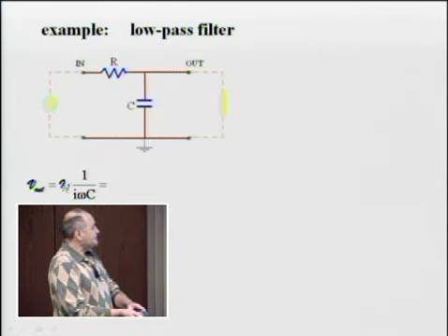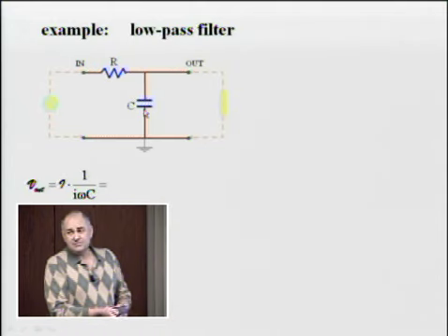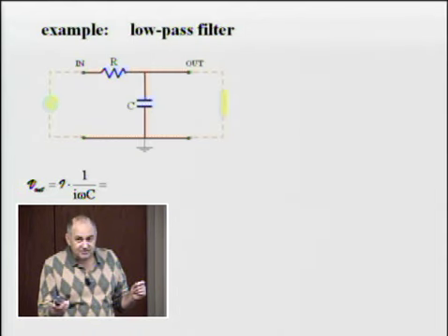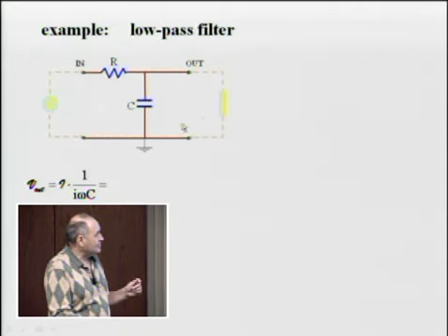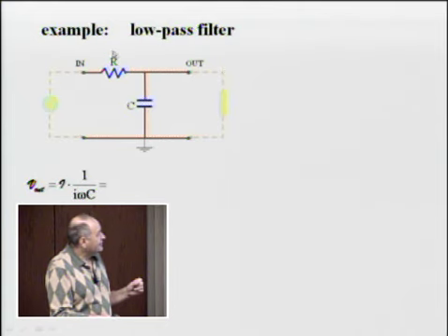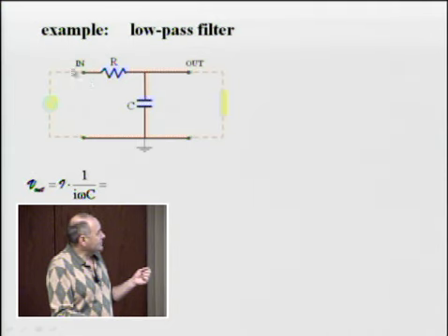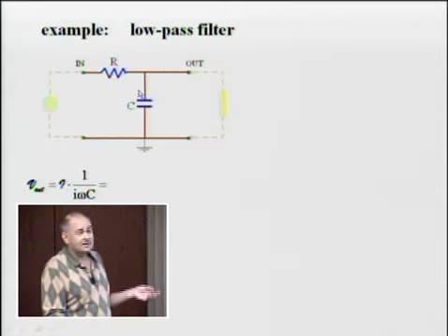Now, this complex current flowing through the capacitor, I again recognize that the resistor and capacitor are connected in series. Well, it's approximately in series. How approximate? It is as approximate as no current flows through the input of this amplifier. So if the input to this amplifier has high impedance, then current practically flows only through the resistor and capacitor. So the two currents are equal, and if the two currents are equal, it means that these two elements are connected in series.